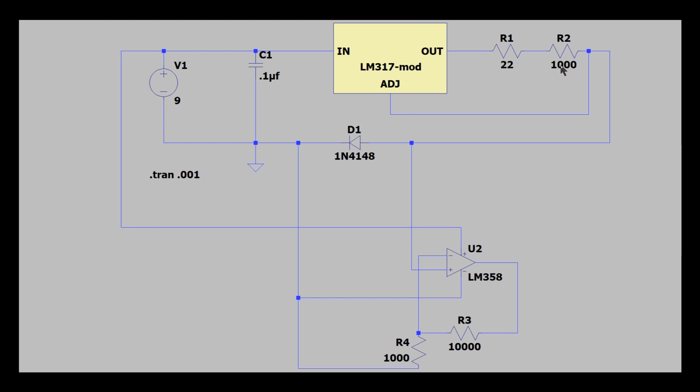Then as you adjust the pot, you adjust the current between this point and as close to 0, which in the case of the LM317 is about 1.2 roughly milliamps. So you can get down to about 1.2. In our case, I think I've got it set up to get us up to, we'll have to look when I get back on the bench, but I think it's about 50 milliamps.